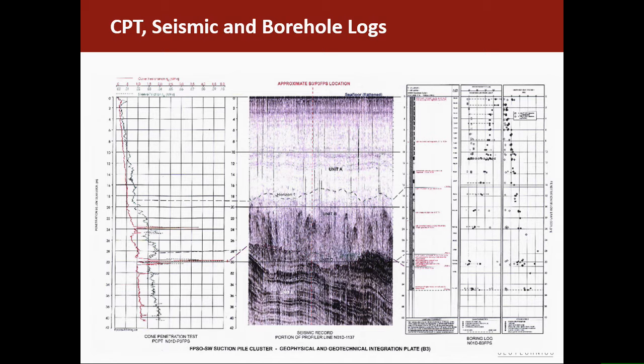And one of the concerns at the time was that we didn't want the piles to go too close to those sandbands, because what can happen is as you suck the pile in, the clay can actually be sucked into the pile and water come in through the sand underneath it, and then you don't get the pile in to depth. In reality, I think that was probably a bit of an overly cautious approach, but it was when suction piles were still fairly new.